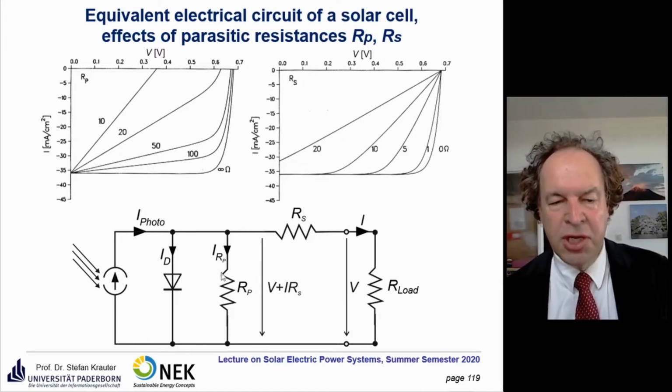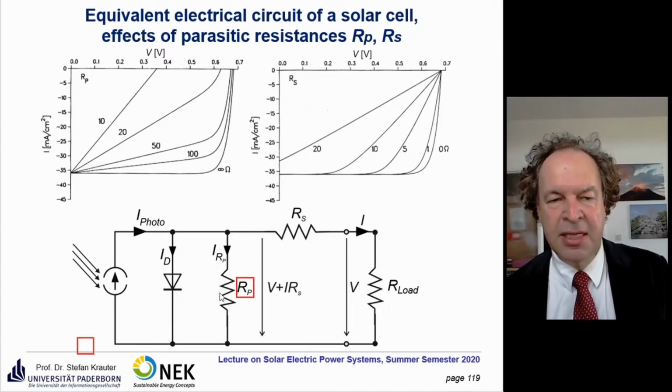resistors, which are so-called parasitic resistors, here in parallel. This is due to impurities and to non-complete edge cleaning. We have some bypass current going through it, so ideally we won't have that RP, or it should be infinite. That is explained on the left part of the graph.